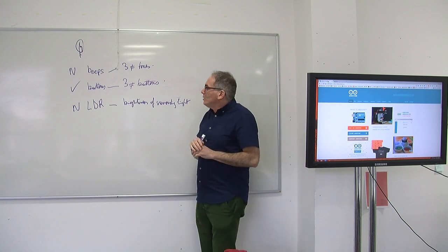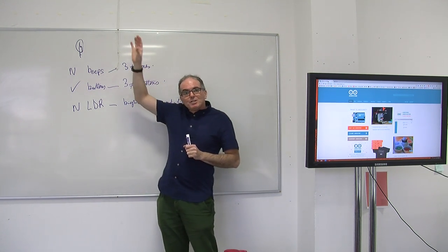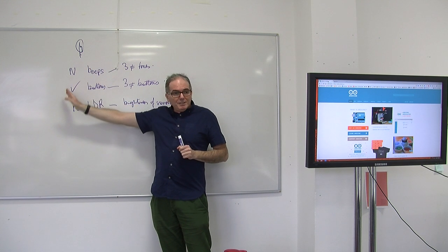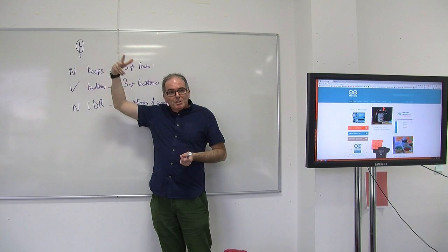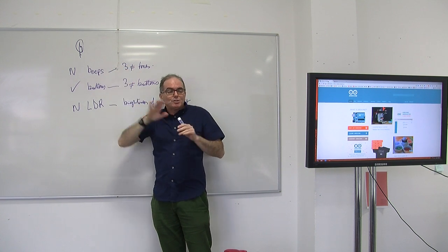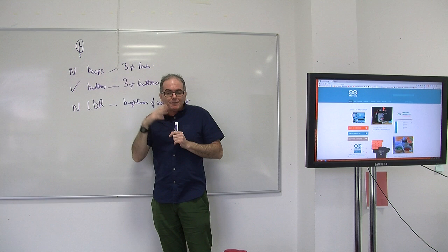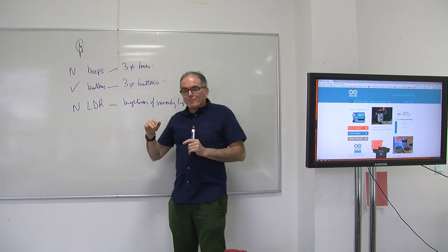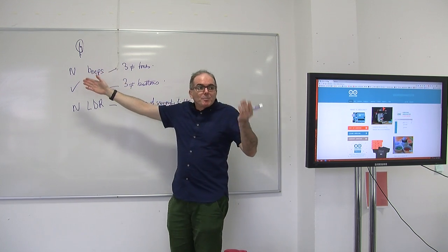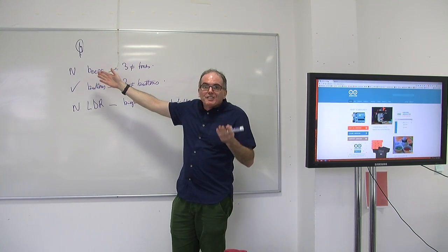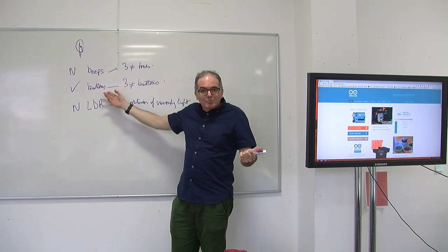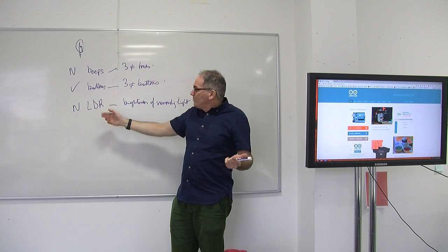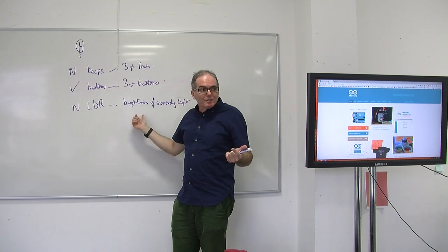Okay. So the translation from the idea to this, you followed, yeah? I said I want a keyboard with 3 keys, and I want the pitch to change according to the light. If it's bright, it's high pitch. If it's not bright, it's low pitch. So that translates into what? We need something that's going to beep, that's going to make a sound. We need 3 buttons, because that's going to be our keyboard. And we need something to see what the light is.